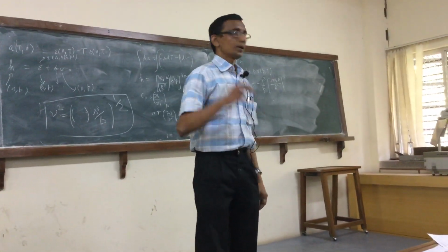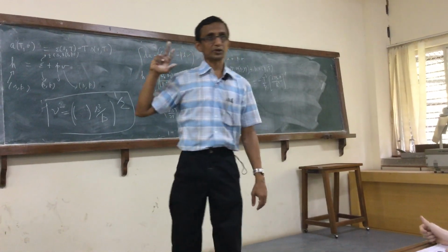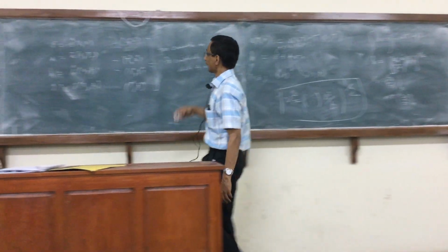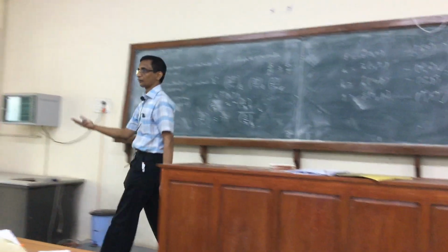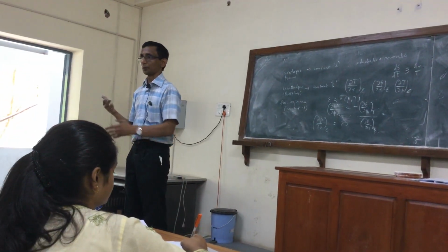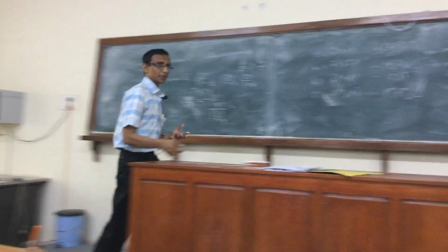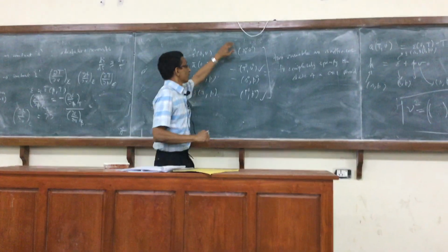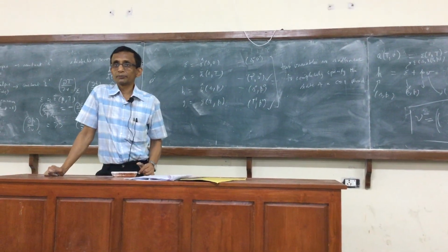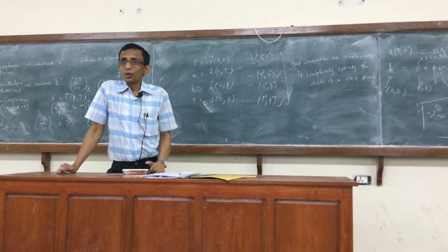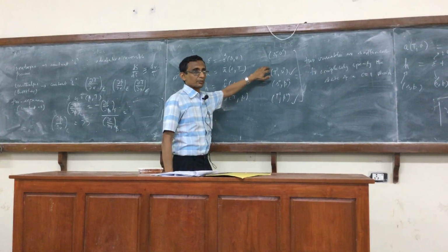You are safe if you restrict your specification to these four sets. And that is why this and this are preferred usually, because it's easy to specify the temperature and pressure or the temperature and density of the system rather than the temperature and the entropy or pressure of a particular fluid, right? Because these are easily measurable, easy to measure, right?